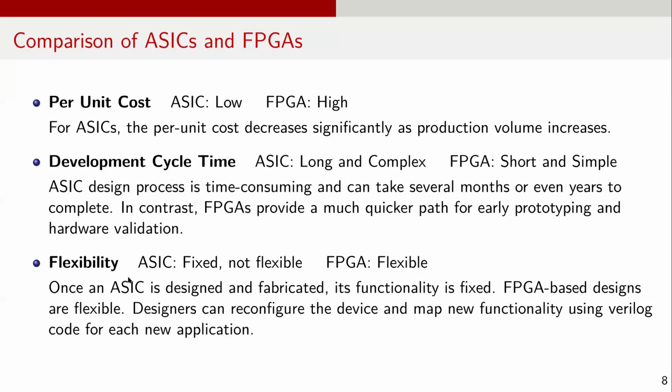In contrast, FPGA-based designs are highly flexible. Designers can use hardware description languages such as Verilog and VHDL along with FPGA design tools to reconfigure the device and map new functionality on the available programmable logic and interconnects without starting from scratch for each new application.